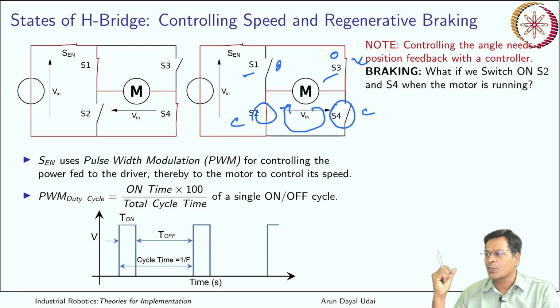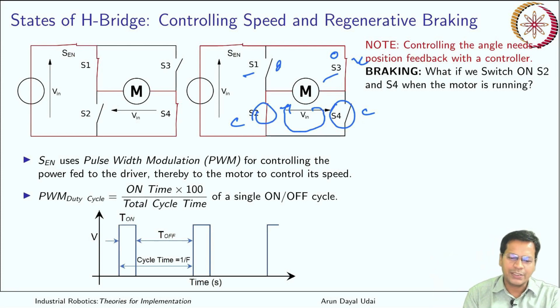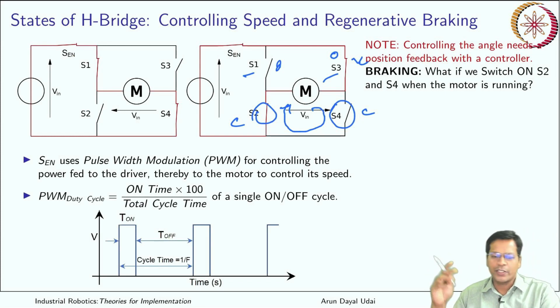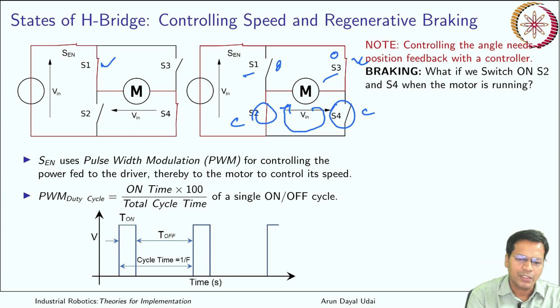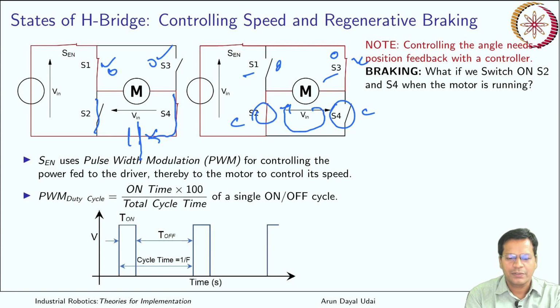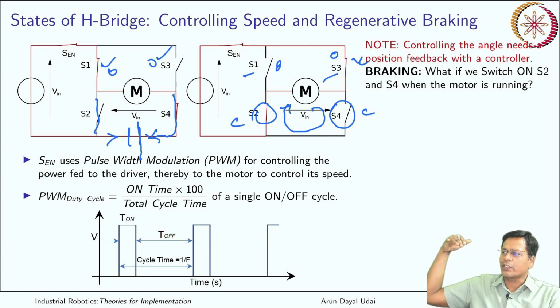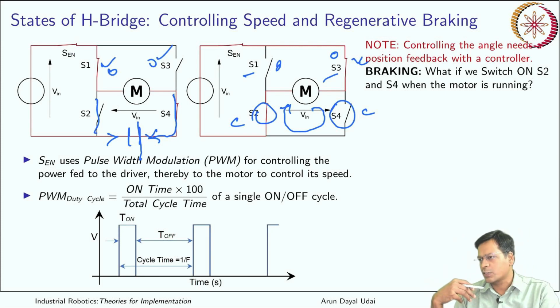But yes, it can bring it very close to the stopping speed of the motor when you can physically apply the brake, right? And more so, let us say you can use this motor to generate electricity when you are not supplying it with power. By opening this too, you can have a battery here, which can be charged by having the motor running in idle condition. Let's say your robot is going downward on a slope. Now you can use that power.